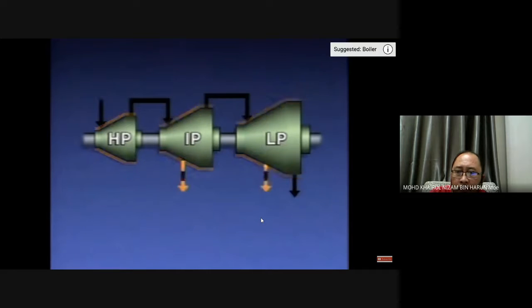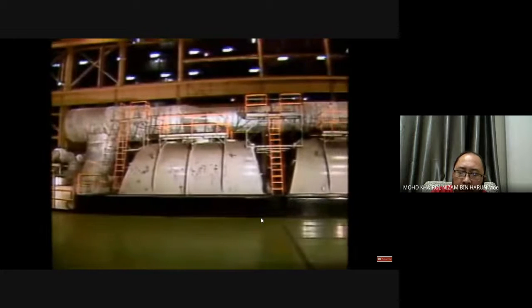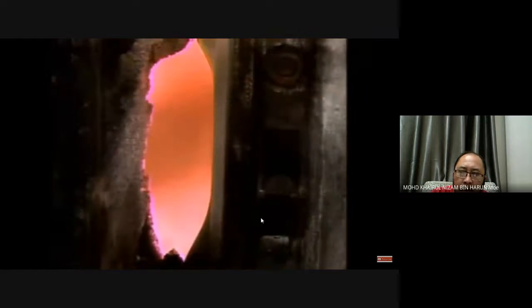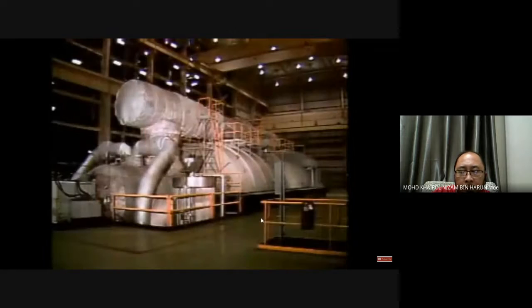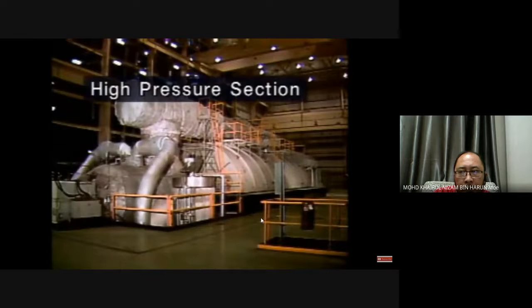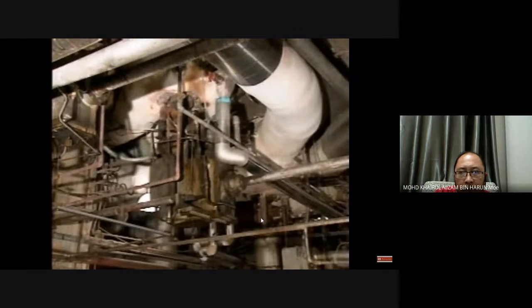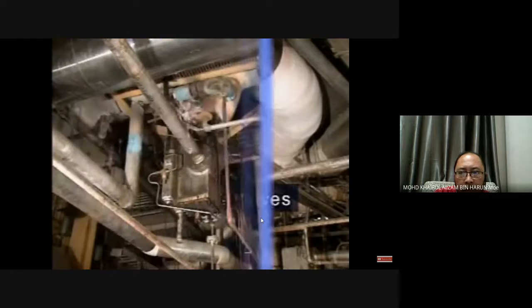Second, some of the steam is removed from the turbine by an extraction steam system. The extraction steam is sent to the feed water heaters, where it is used to heat feed water. The steam in the turbine gives up some of its heat as it passes from one stage to the next. For this reason, it's often necessary to return steam to the boiler for reheating before it passes through the entire turbine. This reheating most often occurs between the high pressure section and the intermediate pressure section. Reheated steam is returned to the turbine through reheat stop valves and intercept valves.